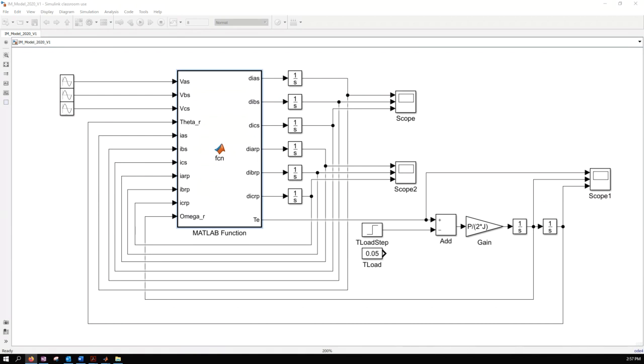And this is the mechanical equation. Okay, we are familiar with this. We've seen this in DC machines. We've seen this in synchronous machines. We have two integrators. Since the output of the torque equation is acceleration, this is speed, this is position. Both are needed for the simulation.